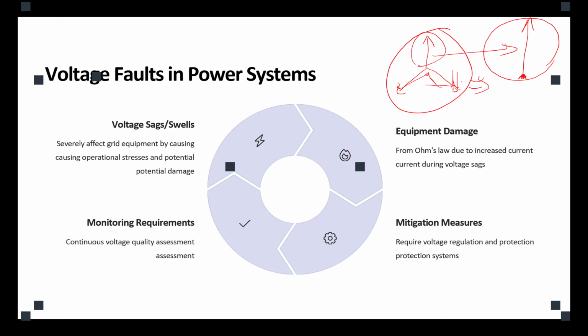If a fault happens, it's an Ohm's law situation. If we have a short circuit, what does that mean? That means we face a very low resistance between a high potential and the ground. Or, to be more precise and rigorous, between very different potentials, we have a low resistance connection.